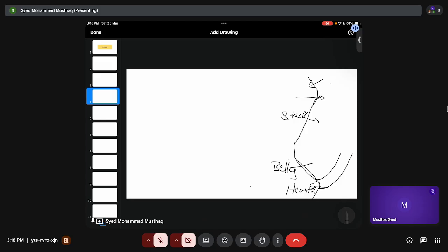Because of this, here you have a very active zone. The active zone is nothing but where the air you are purging is continuously reacting with your coke. So this is called an active zone. It continuously reacts with your air to produce carbon dioxide, and carbon dioxide can react with carbon to form carbon monoxide. Whatever reaches here will get reduced, and then you have this cohesive zone.